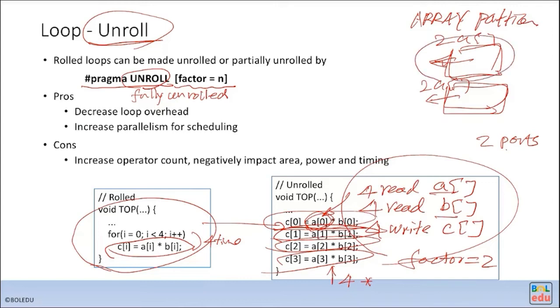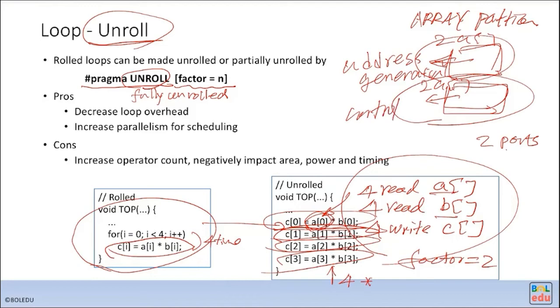The HLS will generate this kind of circuit logic for you, and it generates all the address generation and all the control for you. So you don't need to worry about the detail of how the logic is designed. You simply use this pragma, and then the HLS generates all the necessary control logic and data path for you.